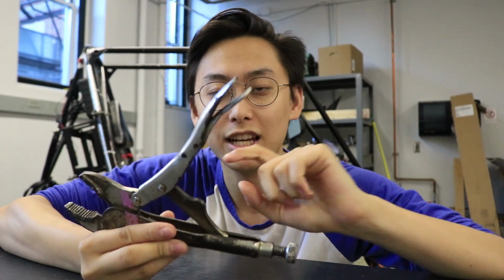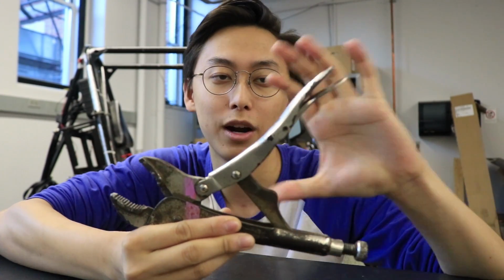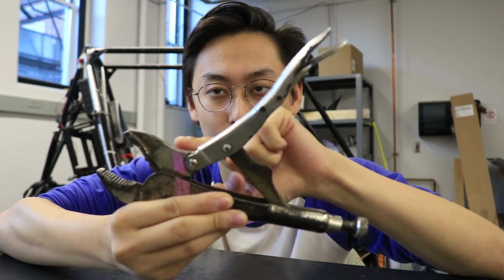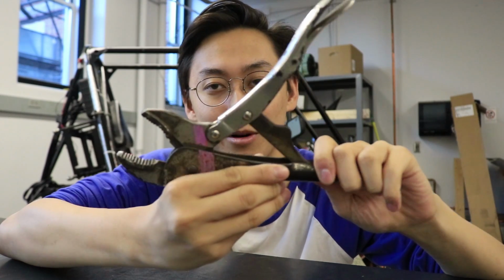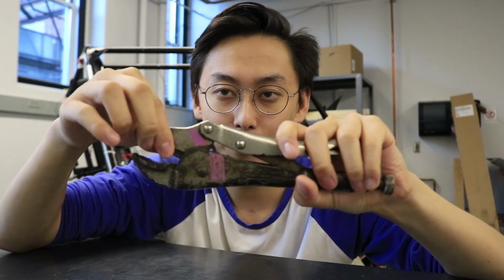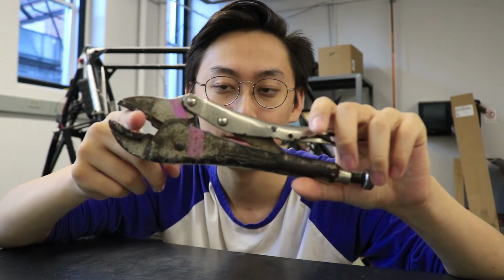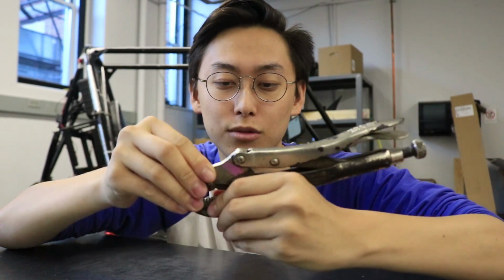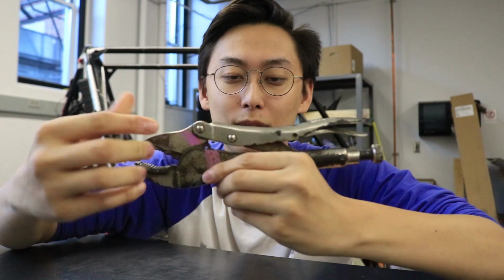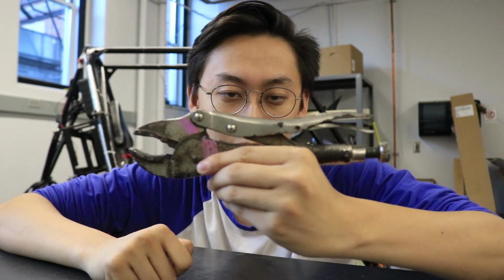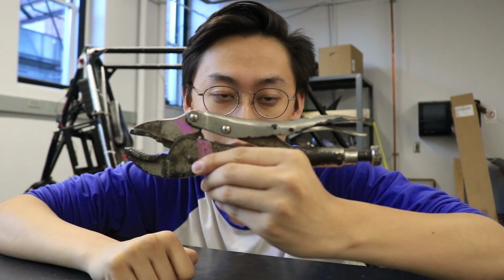How a vice grip works is that it uses the exact same concept: when you press this 4-bar, so 1, 2, 3, 4 bars down, the grip part locks in place because that is the bar that is moved in the 4-bar. And now, no matter what you do, if you judder this, you can't move it because these 2 bars are in the locked toggle position.